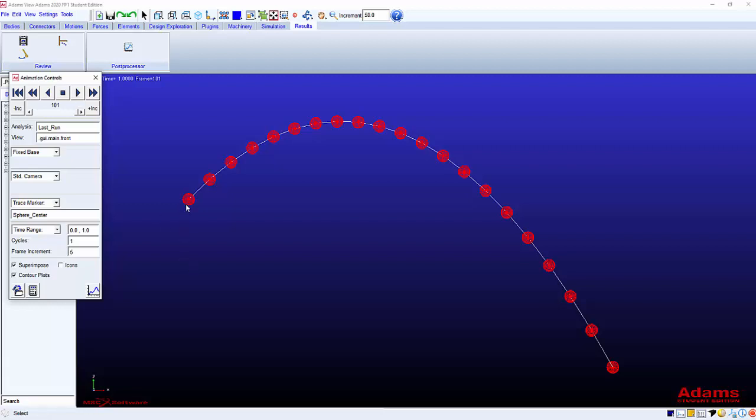At every frame that Adams plotted or Adams drawn, Adams is going to keep that frame and build the next one. Sometimes this feature is useful if you are interested in learning or studying the range of motion for certain applications. Or sometimes you will be interested in learning about the working envelope for certain mechanism.